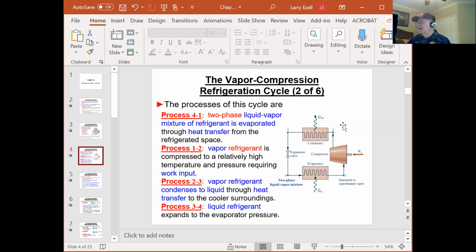Now we go to the heat out of the condenser, the heat rejected, which, by the way, is the heat pulled in here plus the heat injected here during the compression process. So let's look at this. We want it going out positive, so we want to go with the arrow. The higher energy state is H2, so Q out is going to be m dot times H2 minus H3.